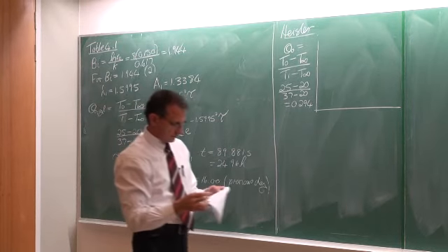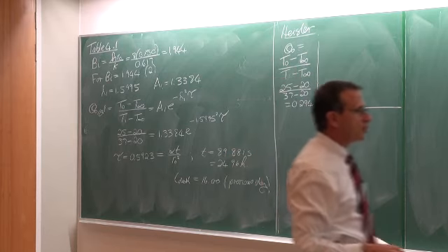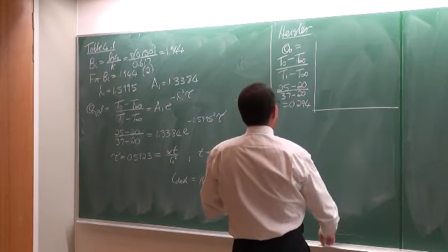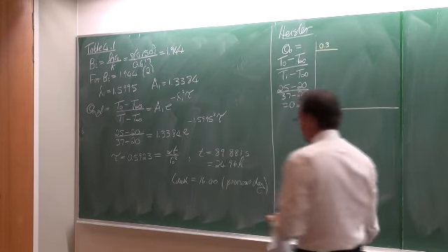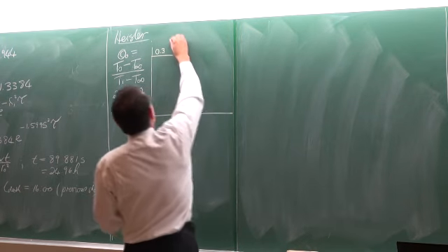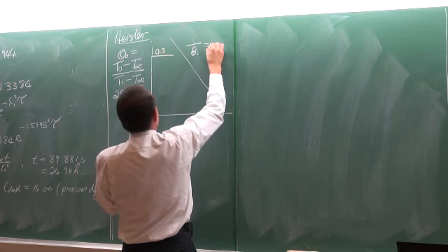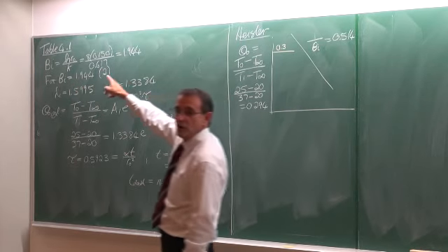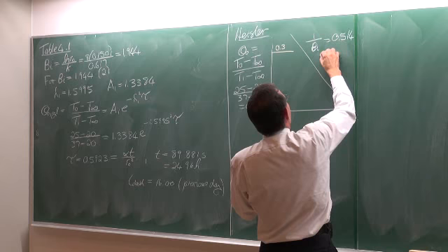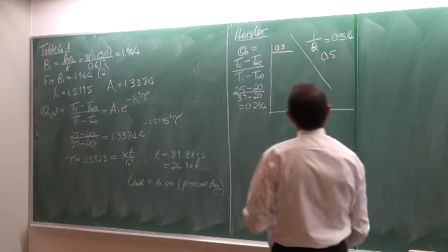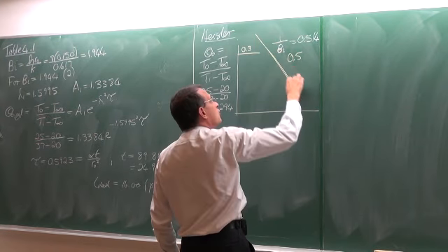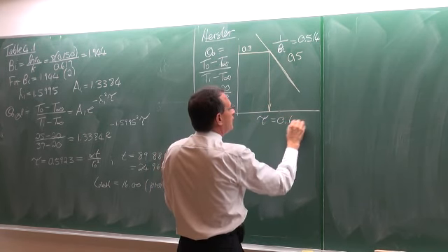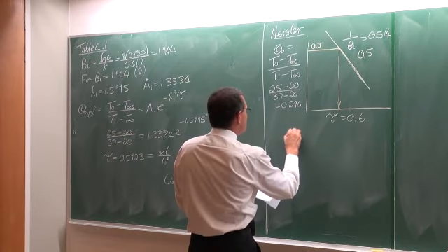Now, if you look at this graph, there's no way that you can read off a value of 0.294. I've tried my best, and I could only settle on 0.3. Then we've got the lines of 1 divided by the Biot number, which is equal to 0.514. So 1 divided by 1.944 is equal to 0.514, and I could only manage the line of 0.5. For the line of 1 divided by the Biot number equal to 0.5, I could read off a value of tau of 0.6.